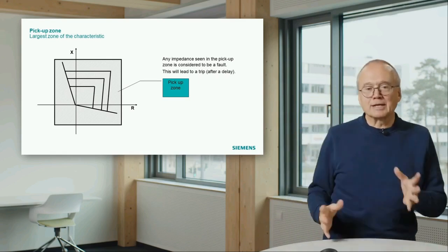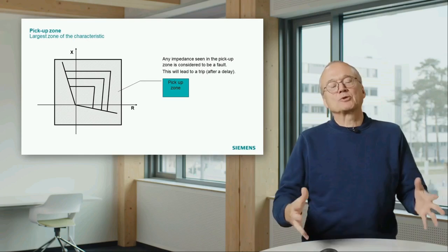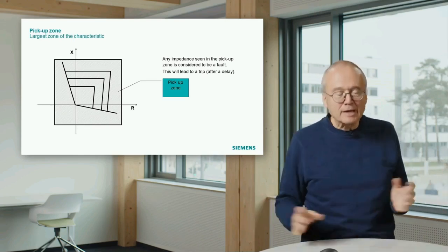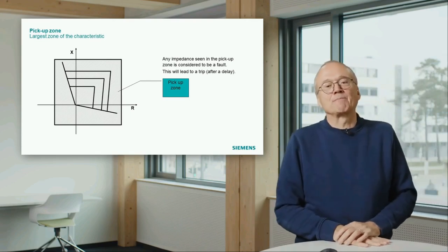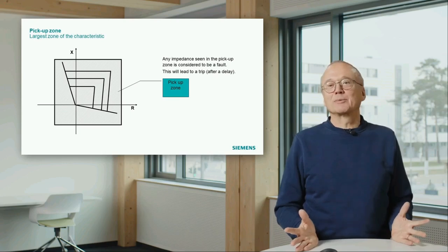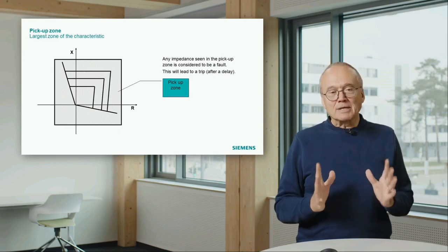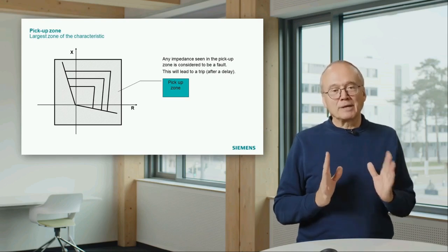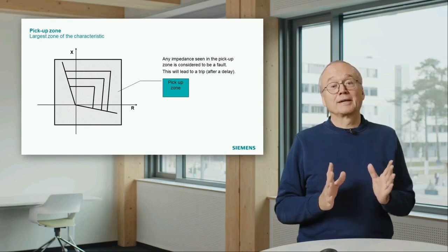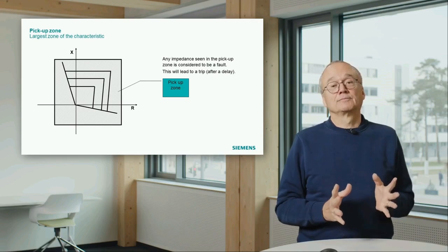You normally have delay times, so all zones have delay times. That means the pickup zone typically has the highest delay time. So it may have a delay time of a second. But if it moves in within a second, the control center is not able to react on that. You will trip. That means if you define your pickup zone, you must be pretty sure that you don't run into the pickup zone in normal operation.